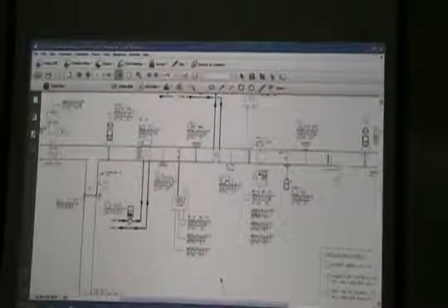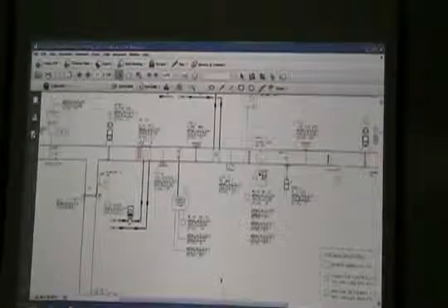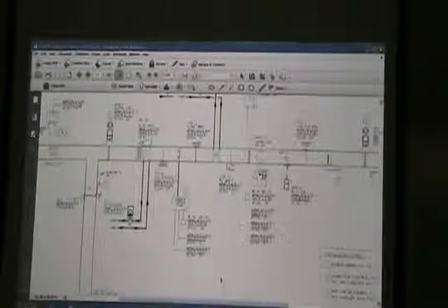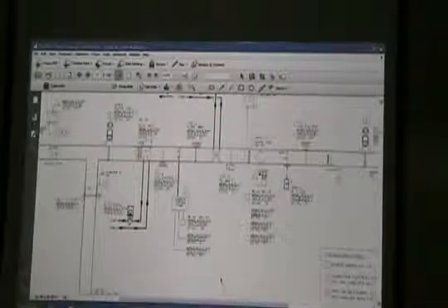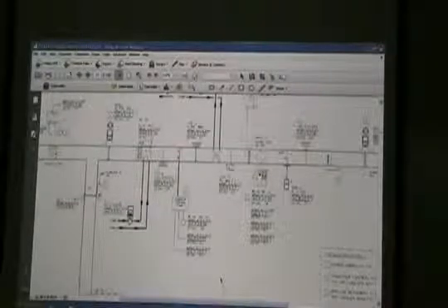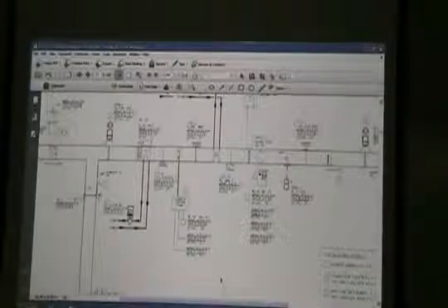So when the mixed air temperature is below 39 degrees, the preheat valve should be fully open, this device right here. And again, the reason he wants it fully open is to protect that coil. We have constant water flow through those tubes. It's less likely to freeze. Even though this is a hot water coil, as long as we can get water flow through it, it's less likely to freeze. When the mixed air temperature is below 39, the preheat valve is going to go full open, and the face and bypass dampers should modulate to maintain the supply air temperature.